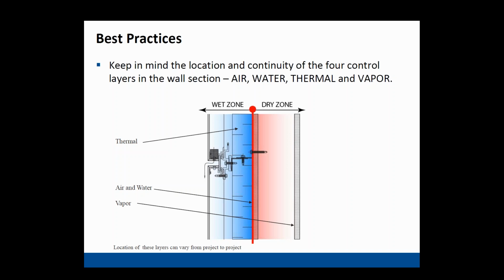Yes. This diagram here also shows the whole wind criteria in a little graphic, as you can see with the fasteners. As architects, what we normally specify is that our structural engineer is going to address the wind loading requirements for cladding loads on their drawings, or we include it on our drawings, so they supply it to us. And then there's usually a delegated design aspect to our specification where the people doing the attachment system, or maybe the fabricator of the MCM themselves, have to hire a PE to validate, given the loading criteria on our documents, that the assembly being put on and its attachment methodology will meet the loading criteria, because we don't get into screw spacing and things like that, but obviously the installer does.